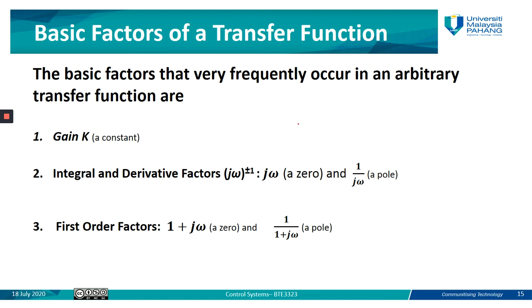Okay, but if we want to draw this Bode plot by hand, I mean manually on semi-log paper, we can split or divide our transfer function into some parts, and we draw each component individually. Then at the end, we are going to combine all drawings into one plot for magnitude and one plot for phase. So usually the transfer function consists of some specific or standard elements, okay.